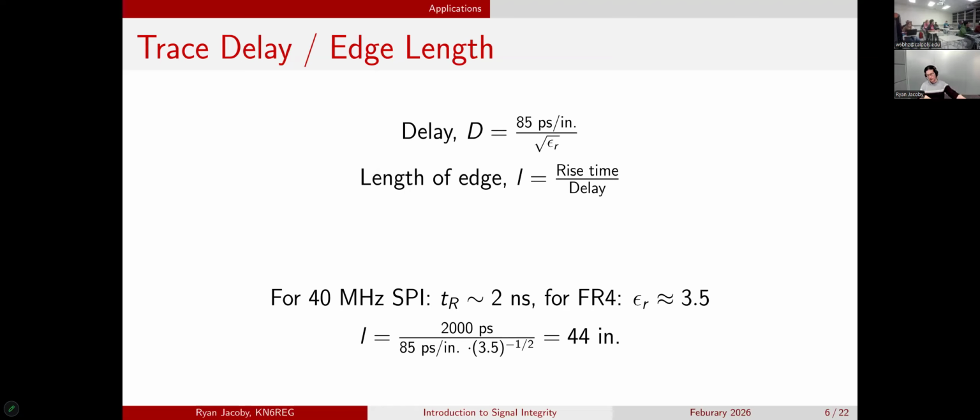you would have to really consider the layout, consider the source impedance, line characteristic impedance, termination on that, and all of that sort that we're going to get into. So, 4.5 inches on a PCB is rather long. Generally you don't want to grab a high-speed signal and pull it from one side of the board to the other. Sometimes you obviously really have to, but where you can, I guess this is one of the first things: keep any fast or noise critical portions of your circuit small and close together on your board. That helps a lot.